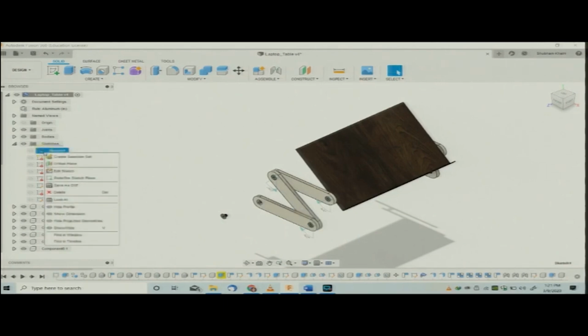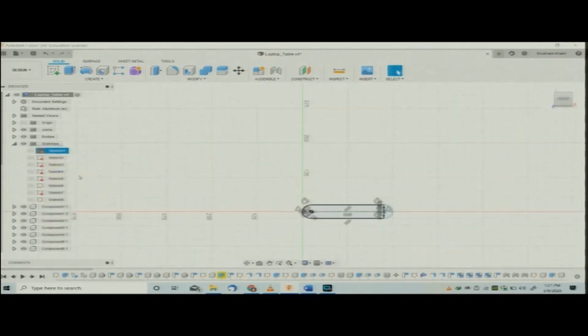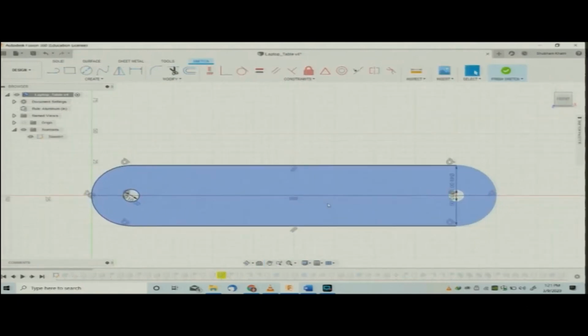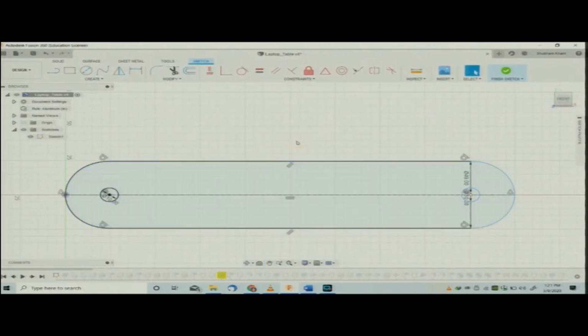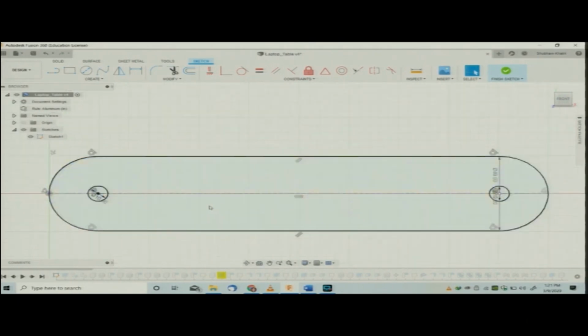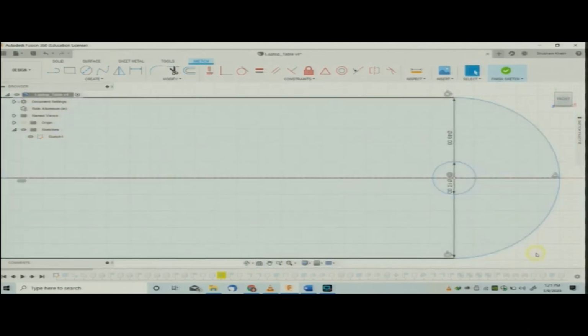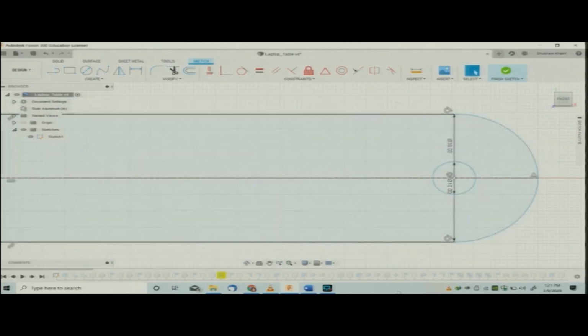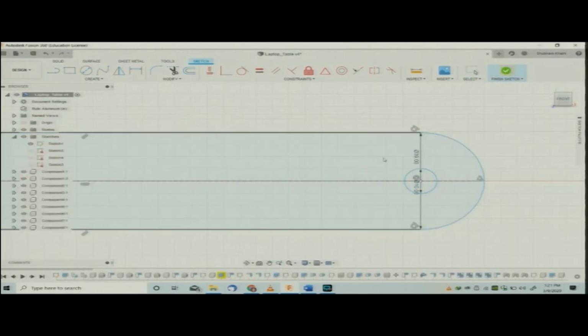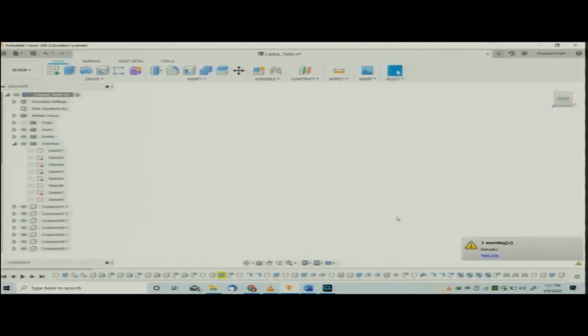So, let me try this. This is the sketch. Right click on the sketch, edit sketch. So, in this sketch, we have the dimensions here. We are allowed to access the 2D sketch environment directly. Here the dimensions were already put as 49 mm dia and 10 mm dia. For this component, if I make a change here, for instance from 49 to 39, see, this dimension is changed. I am saving it. It will automatically reflect in our 3D geometry.